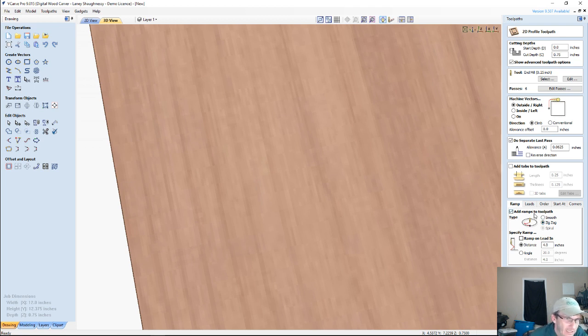Do we zigzag in, meaning the bit's going to kind of zig from a shallow depth down and then to another depth to our final cut and then lead in? Or are we going to do a smooth lead, where it's just a little additional circular ramp to our lead in? So it's not just plunging straight down in the lead in to that 1/8 of an inch or whatever my pass depth is. It's gradually cutting down to that depth, slowly starting from 0 down into the cut till it gets to the depth and then around.